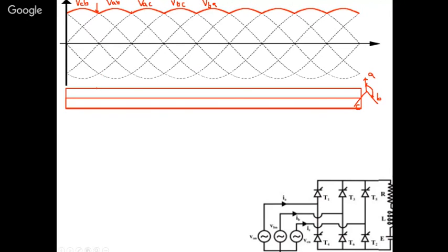So here, first we will be firing a thyristor T1 at this instant. This is your T1. Okay, and this point, that is 120 degrees, because when a particular thyristor in a particular phase is fired, it remains positive until the phase, say A phase, is more positive.